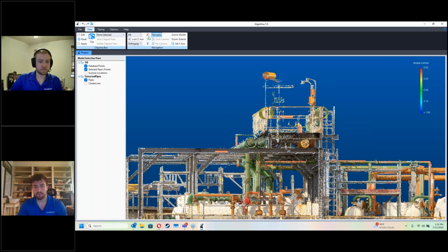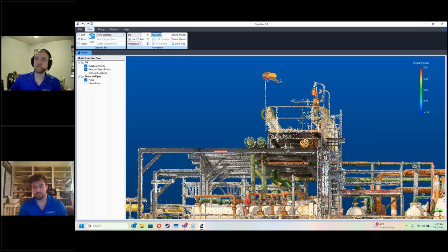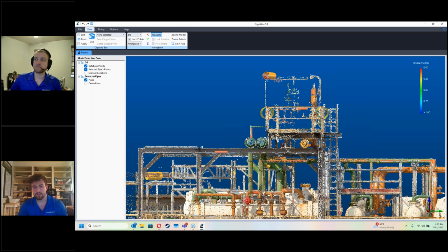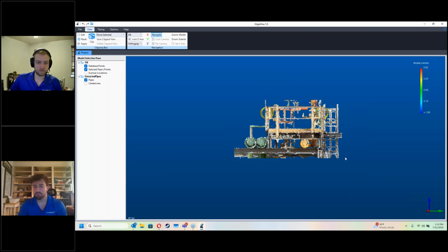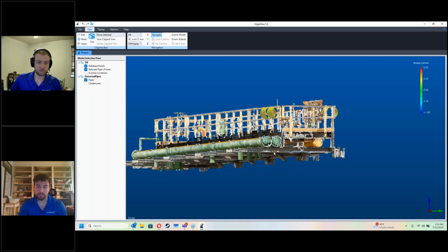So for example, if I hop on my X, it's a little skewed, so I'm just going to take over and manually align that. To actually do the clip, I'll hit the clip button right here. I'll do a single left click, draw this little red line, left click again, and turn the line into a box. Once I have that box drawn, there we go, we've performed the clip.